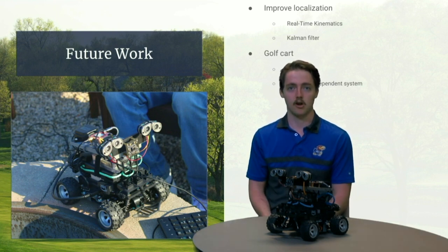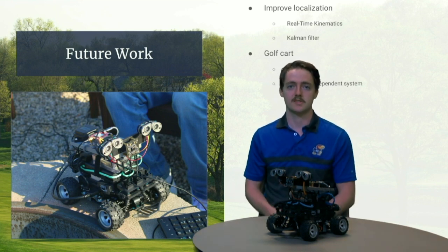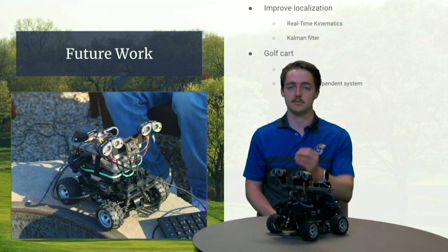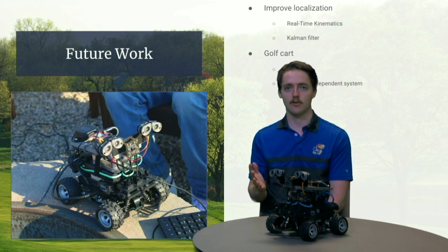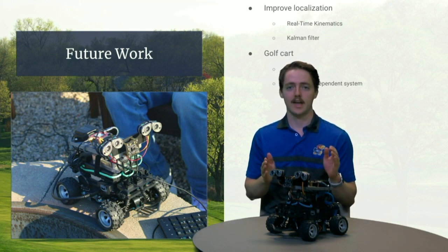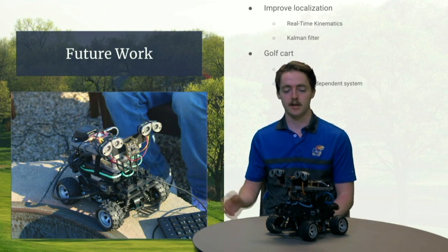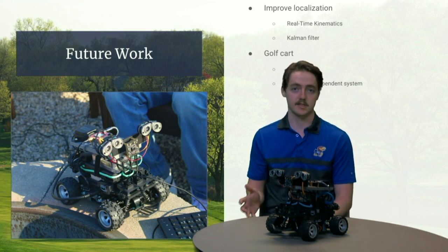The other approach is called a Kalman filter. Using our GPS data and information from the IMU, we can perform sensor fusion in order to get a much more accurate GPS location. Another obvious change that we'd like to see is to implement CADD-E onto an actual golf cart. This would be a fairly straightforward change, as CADD-E is a very platform-independent system. The biggest change would be modifying what actuators actually carry out the controller commands. So instead of using the DeepRacer servos, we would need to implement a couple different physical systems on the golf cart in order to control it the way that we want.